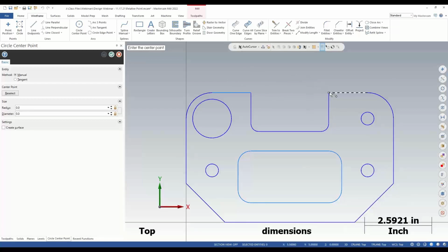Well, if you guys ever notice when you hover your mouse over a specific point, a little green plus appears. At first, nothing happens there. But if I go over another point in space and hover over that for a second, another green plus appears and a red plus appears between them. That's what's known as temporary midpoint. And then I can now come over here, click on the red point, and that's the perfect midpoint between those 2 points. So if I said I wanted to get the midpoint between this midpoint and this midpoint, get that.